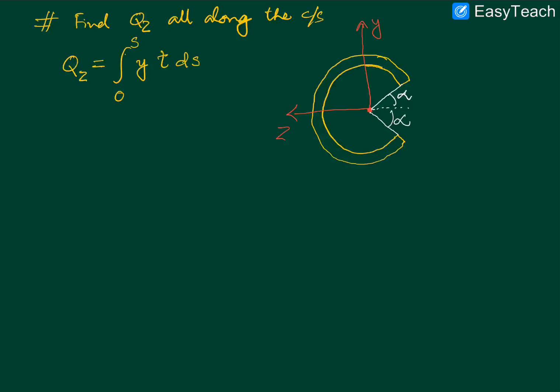I again emphasize here that as we had discussed in the previous lectures also, this t has the same value all along the cross section. It is possible to have a theory where this is perhaps varying, but that is just an extra complication without much return on investment as far as the physical understanding is concerned. So we'll just stick to this simpler case of a constant thickness all along the cross section.